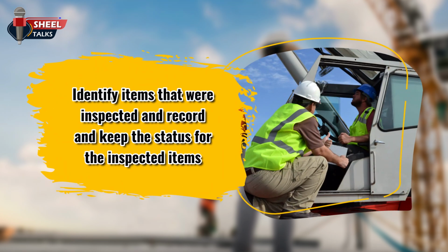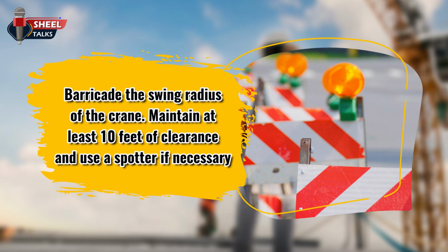Identify items that were inspected, and record and keep the status for the inspected items. Barricade the swing radius of the crane. Maintain at least 10 feet of clearance and use a spotter if necessary.